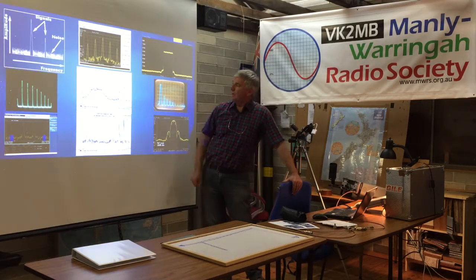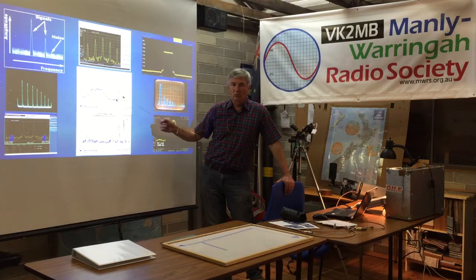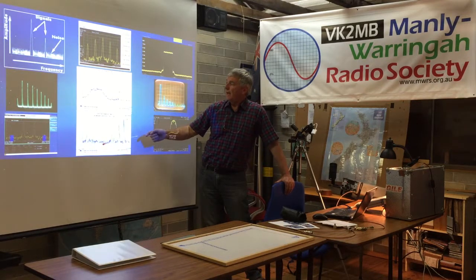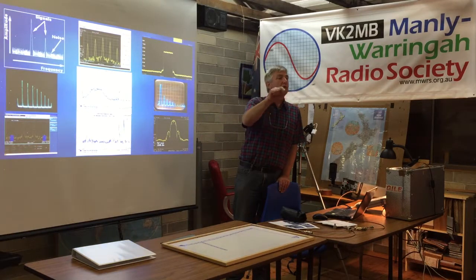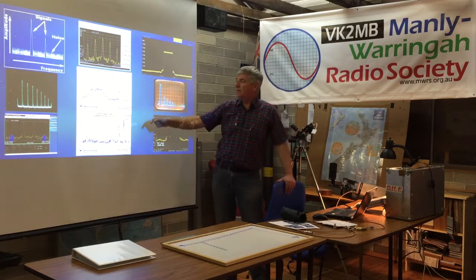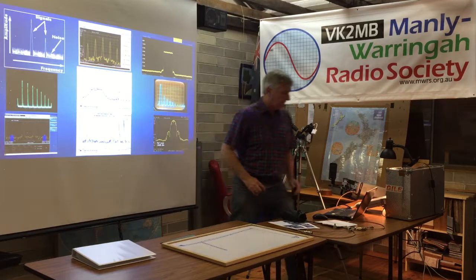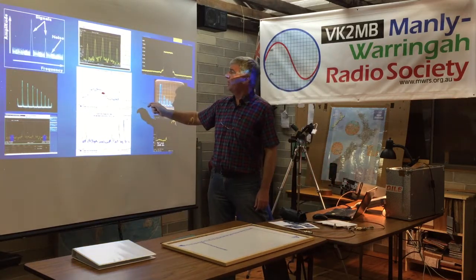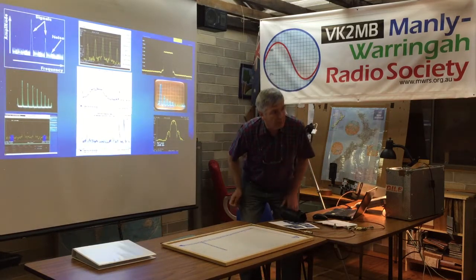So that's the use of spectrum analyzers. Without a spectrum analyzer, things like this are really hard to find. And I should also add that to hunt down where it was coming from, Bruce actually used one of those sniffing loops that we built as a project here some years back, with that blue hard line. Yep, that's what he used to actually find out what it was. It was wideband from about 300 to 500 meg. We're just switching a regulator for a LED light in a shop.